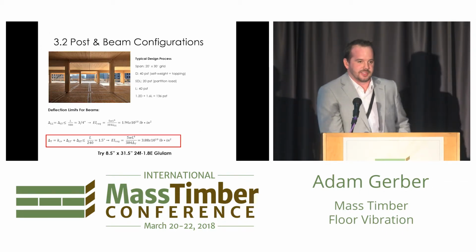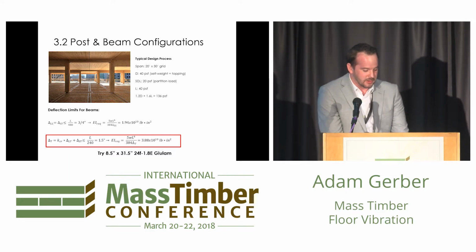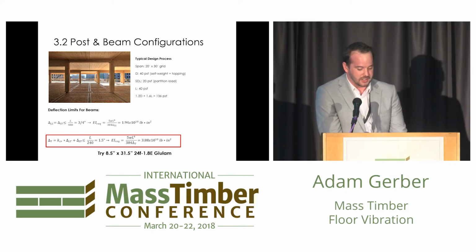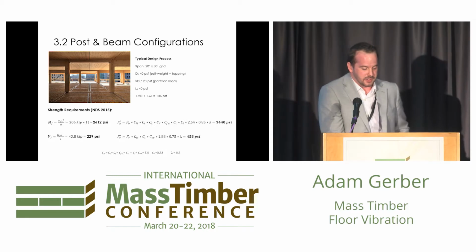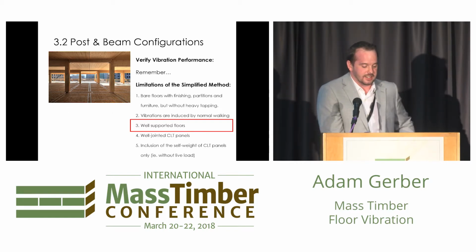So what happens if you want to knock out all those walls, have a nice big open space, and you've already gone through the work and you've sized the panel, and so now all you have to do is size a beam. And so we go through and we size a beam, again for deflection, 30-foot span, check the strength, and now we're back to verifying vibration performance.